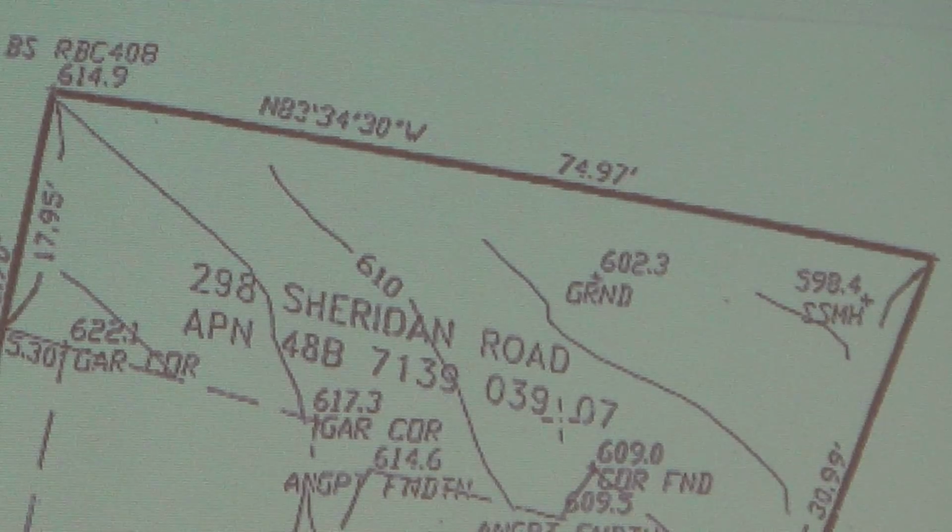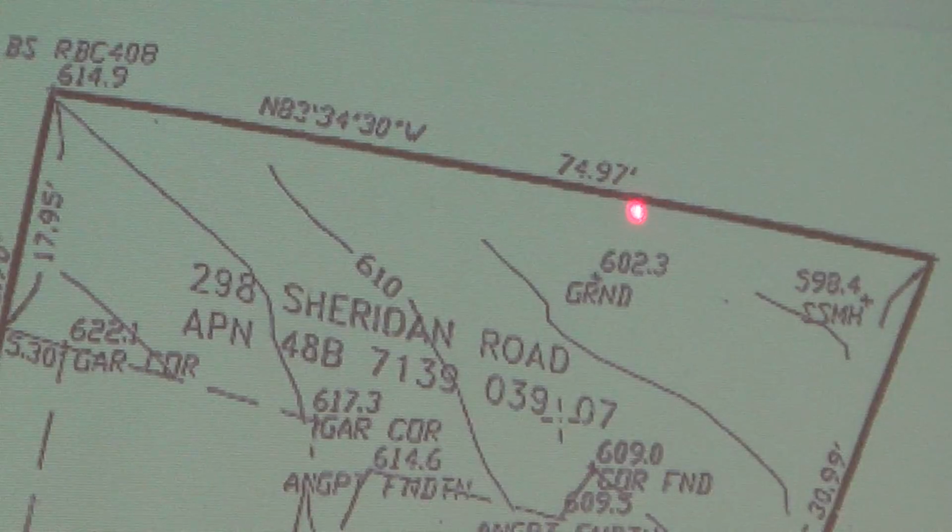So the question is whether it's a horizontal distance or a slope distance. Anytime you see a distance that's representing a horizontal line, the distance is always a horizontal distance. Okay, and now why is that? Let me draw it over here.